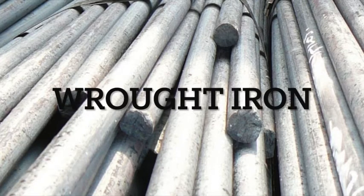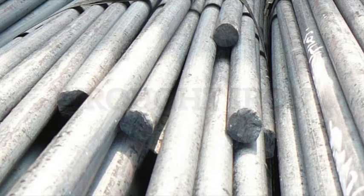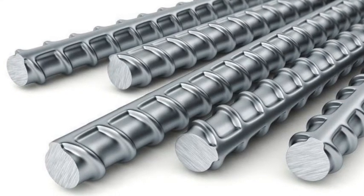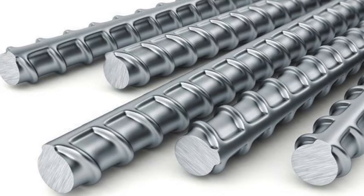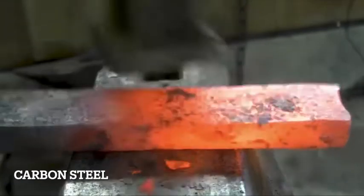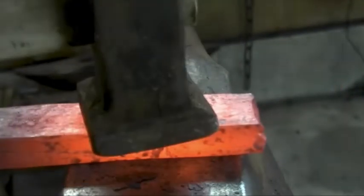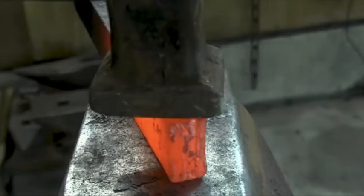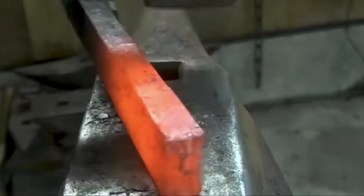Wrought iron. A tough, malleable, relatively soft iron that is readily forged and welded, having a fibrous structure containing approximately 0.2% carbon and a small amount of uniformly distributed slag. Steel. Any of various iron-based alloys having a carbon content less than that of cast iron and more than that of wrought iron. Carbon steel. An ordinary unalloyed steel in which the residual elements such as carbon, manganese, phosphorus, sulfur, and silicon are controlled. Kinds of steel.